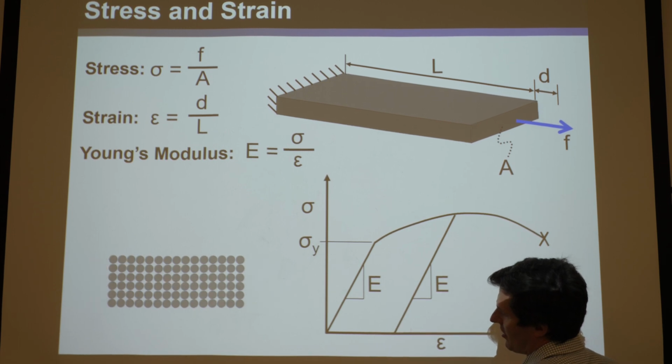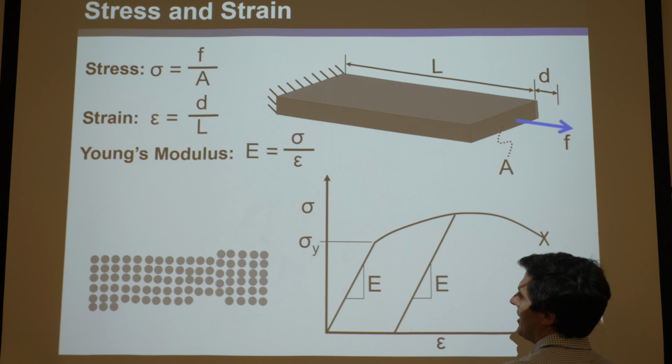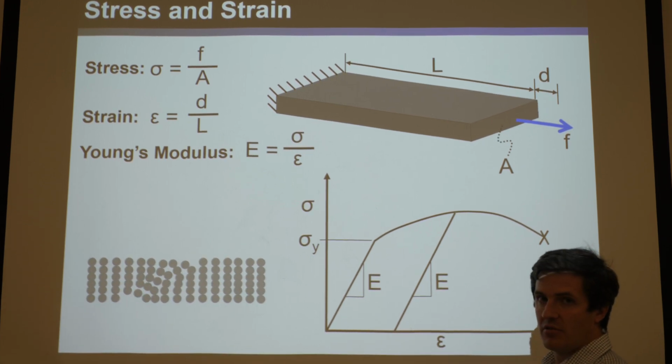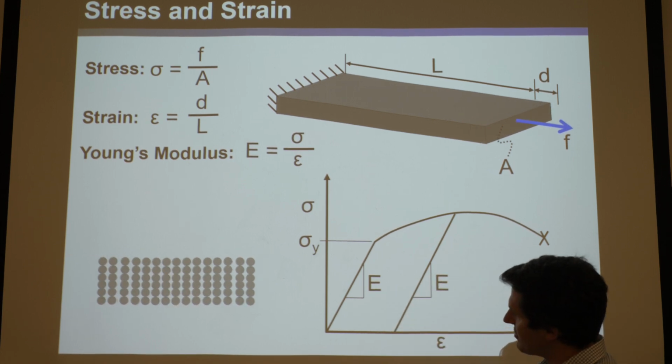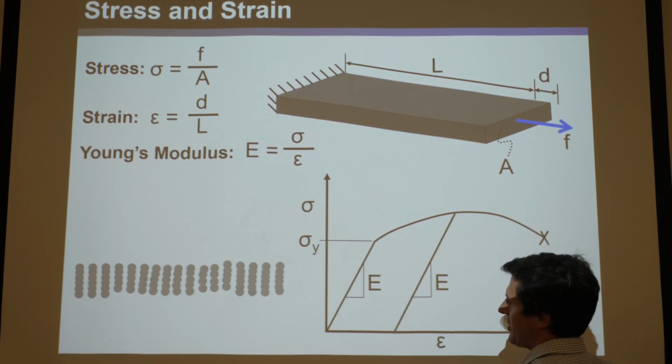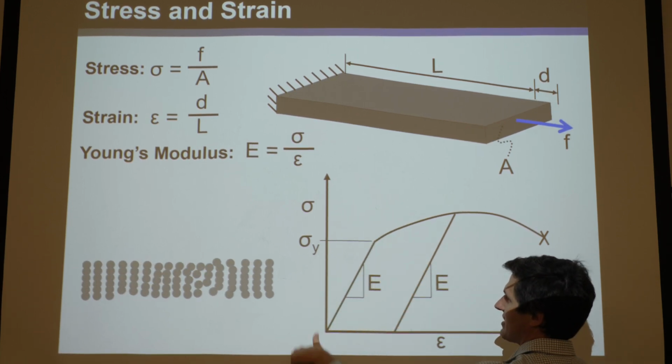But once you yield and you drop it back down, say you pushed it all the way back and brought it back to this point and just kept doing a loop, you'd need to know how many times you looped this, loaded it, stretched it, and then crammed it back in the negative direction. It's going off the page here. But you can get it back to a starting point by plastically deforming it and do these loops.